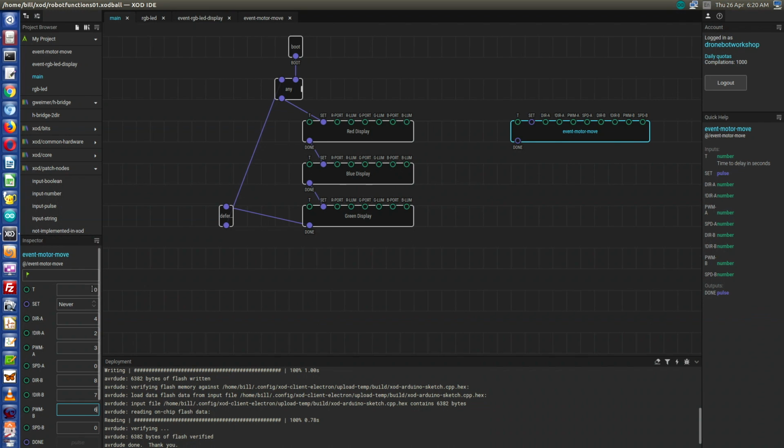Okay, now we'll set a time we want our motors to run. Let's let it run for 2 seconds. And now we have to set the speed values of the motors. Now remember, this goes from -1 to +1, where -1 is full speed reverse and +1 is full speed ahead and 0 is stop, and any number in between is a smaller speed.